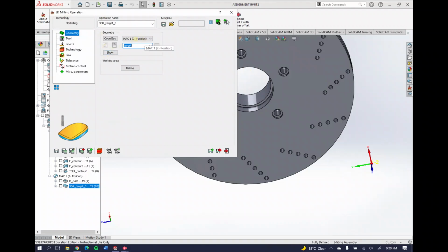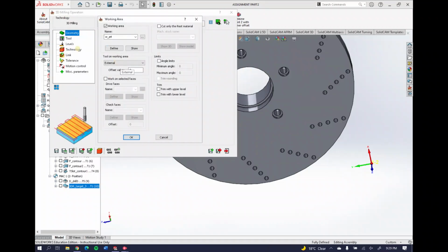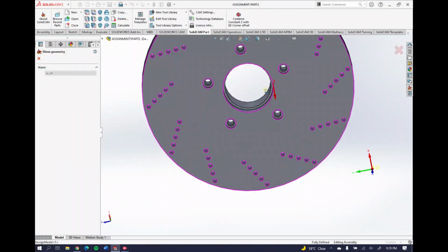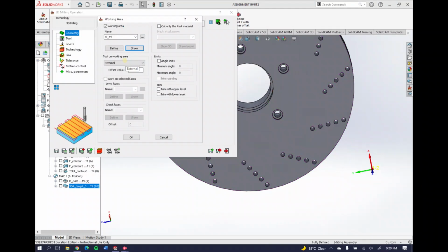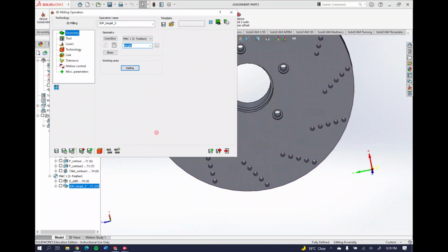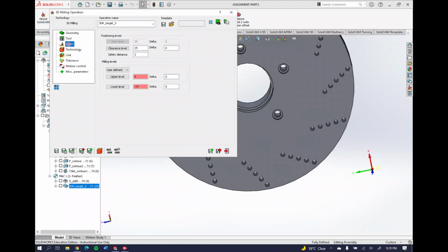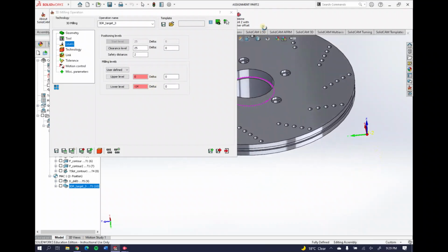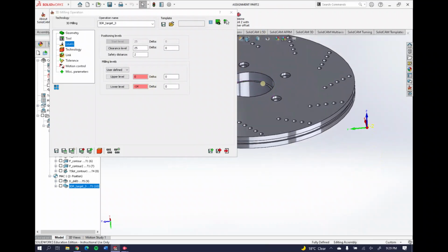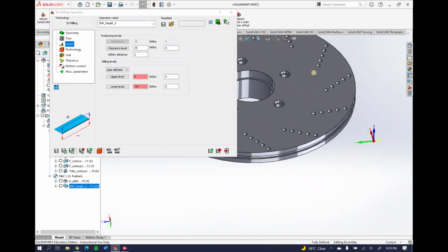And finally, we have the hole in the middle there. And we use position 2 again. It's to work from that face. And I'll show you the working area that we have. So we selected only this hole, since this is the only area that we'll be working on. And we select the 25mm cutting tool in order to make our life easier and to make it a more efficient and quicker operation. And the depth of -14 from this coordinate system. So down here will be -14, starting from the 0 position.